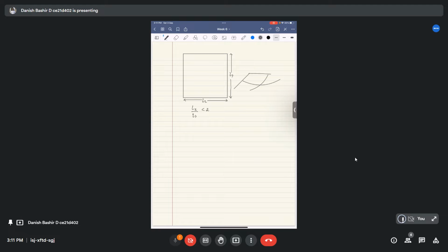If it was the original profile of the slab, it has two deflections, one in this direction and another in this direction. So when the slab bends in two directions, or its aspect ratio is less than 2, we can say that it is two-way slab action.